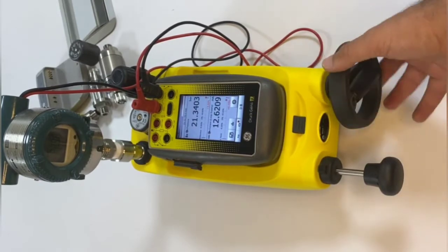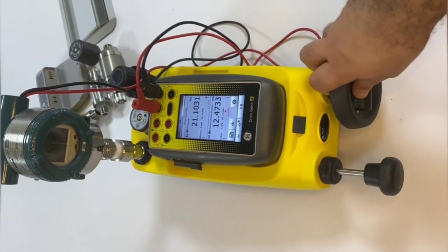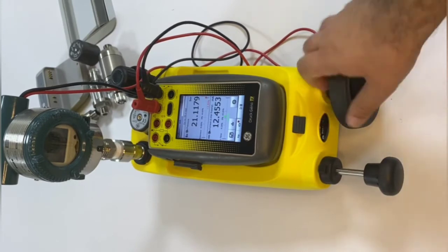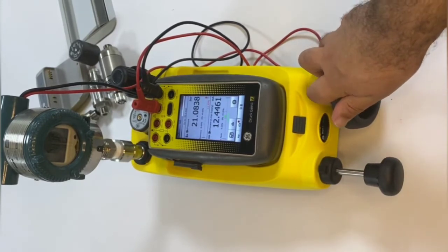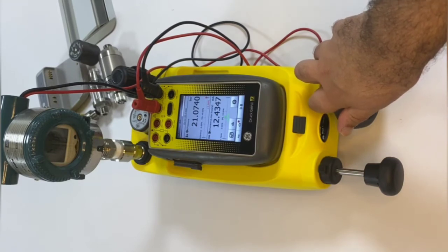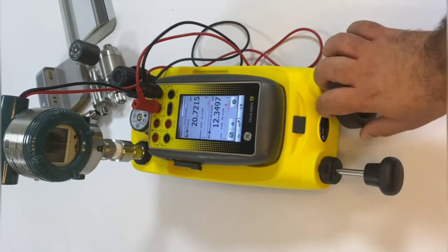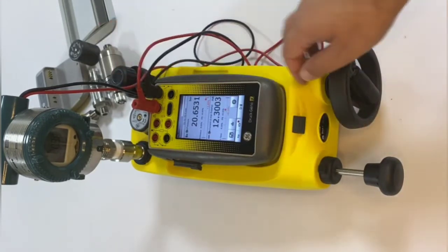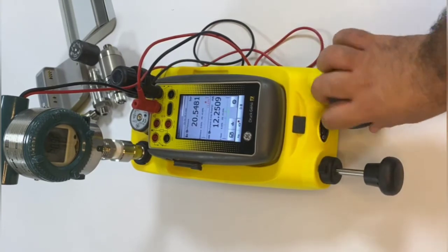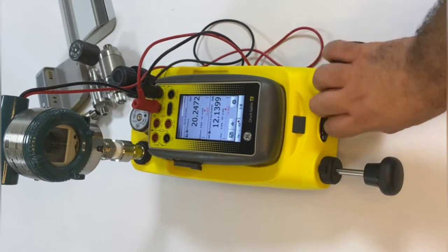So as you can see, just a single rotation will decrease around 1 bar of the pressure. This will give me a very fine control between the points. If I wanted to perform, for example, a switch test, where I need to be precise at the switch latch and the unlatch point. So if I want to drop the pressure faster, I can open the vent. But in my case, I just wanted to show you the fine control for that.